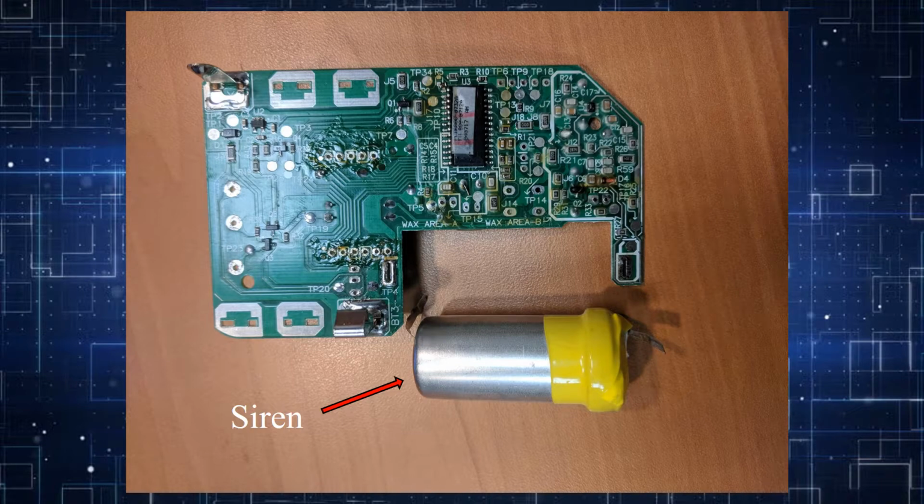Lastly, the carbon monoxide safety siren, which contains sulfuric acid to detect the carbon monoxide level, is most likely manually soldered on the lead side of the PCB board. The siren protrudes from both the lead side and the insertion side of the PCB board, which would mean the siren would be destroyed if wave soldered on the lead side. Also, the solder connection between the siren and the PCB board was messy, which further suggests manual soldering. Alternatively, the siren could be wave soldered if it was initially only protruding from the insertion side, then bent to its final position.